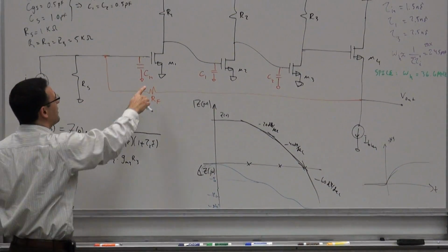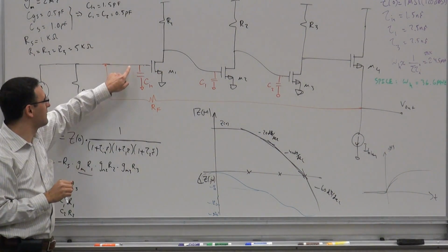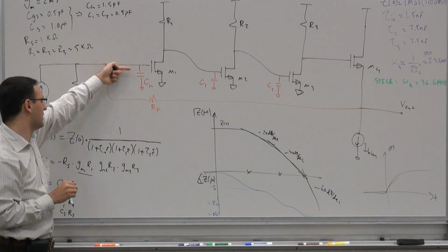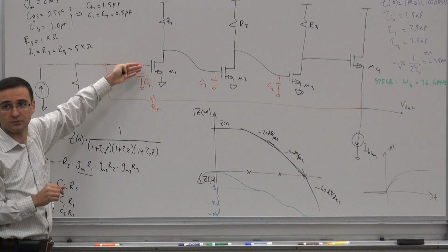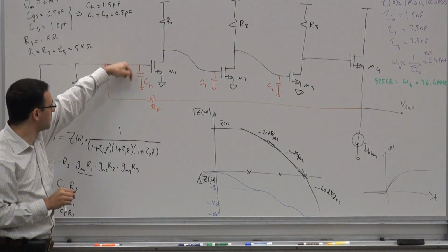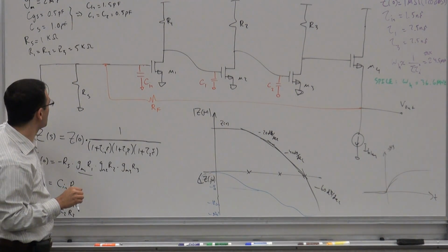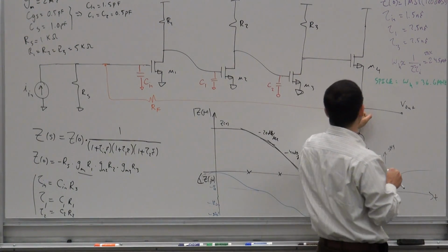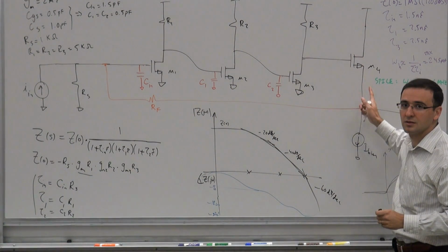In other words, if this K goes to infinity, what does that mean? It means that the voltage at the input has to be zero, and the current was zero anyway, and it will also mean that the current is zero even at high frequencies, because the voltage is zero. So there's no current through the capacitor. There's no current through here either. So what happens is that this current goes directly into here.